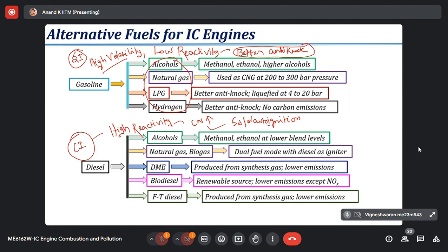Okay, so it needs to have a minimal cetane number. We have discussed that this should be at least 40 according to Indian specifications, right? Not 40, it's above; according to US specifications, around 40. In India, it's around 50. We already discussed all this in chapter 1. So CN should be much higher than 40. Otherwise, there will be a problem of self-ignition or auto-ignition.